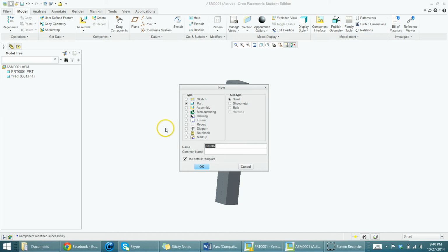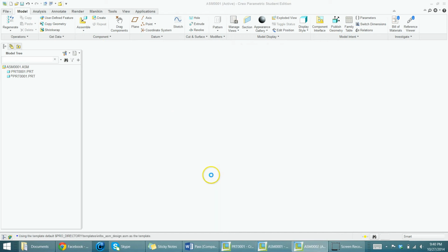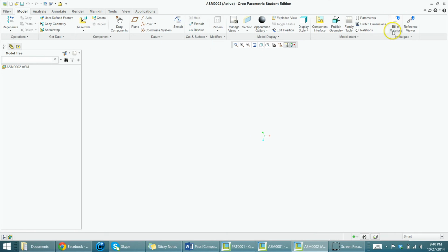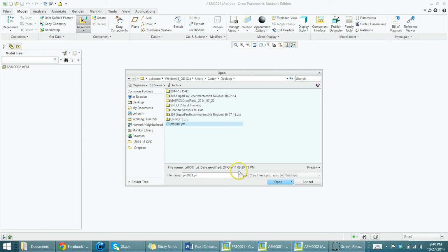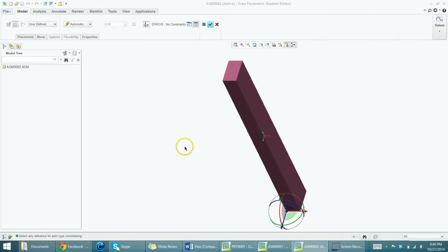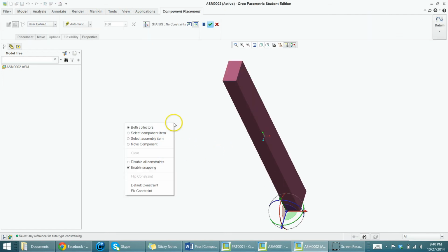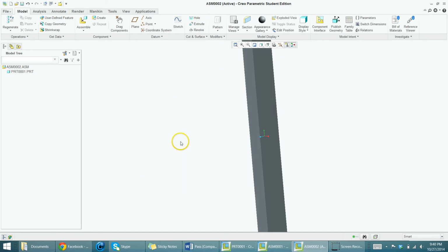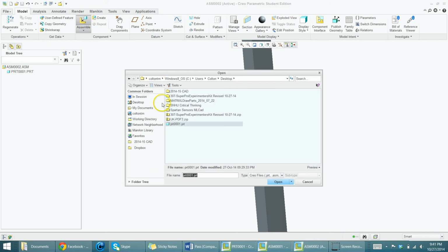So what I'll do is start with a new assembly, because even if you already have the base of your robot made, be sure to make your linear slides a sub-assembly of your main robot. Otherwise, your whole assembly is just going to be a big cluster of madness. So you're assembling first the parent linear slide part, and then make sure that you make up, up, and down, down. So you're probably going to do more than just default constraint on that. And then assemble the next part.